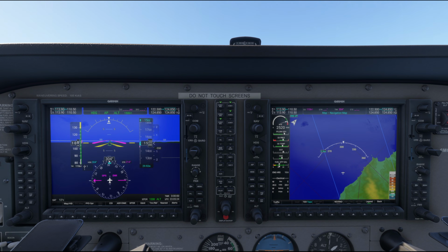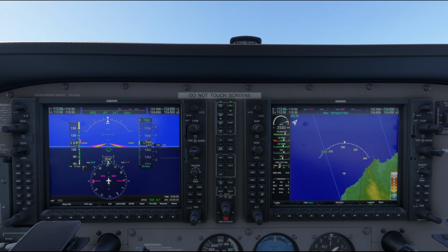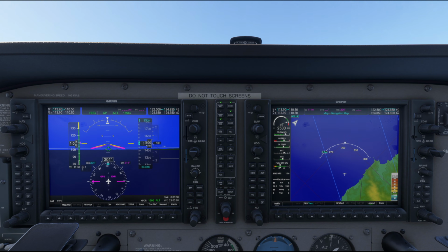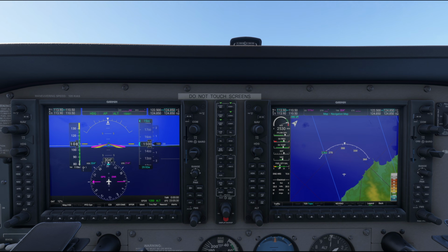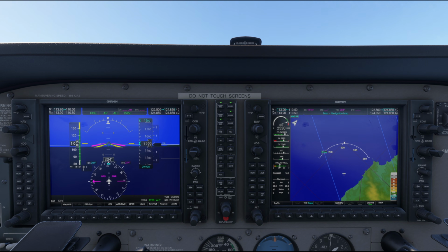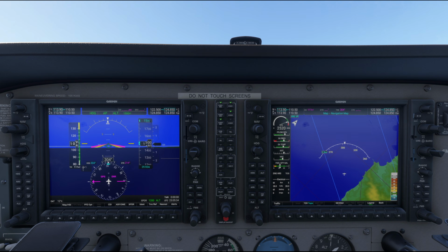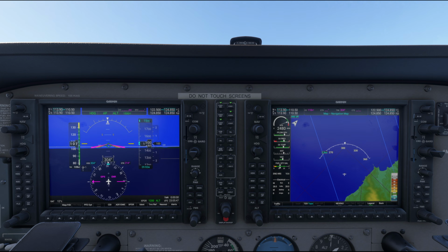Notice that as we do that, the airplane pitches up and down a bit while it settles back to the chosen altitude. This is perfectly normal, but generally it's a good idea to move the throttle smoothly to make this oscillation as gentle as possible. If you were to throttle back without the autopilot, you would likely see an altitude change, and you would have to correct it by changing pressure on the yoke to adjust pitch. With the autopilot, the altitude is held for you. It does that by automatically adjusting pitch.